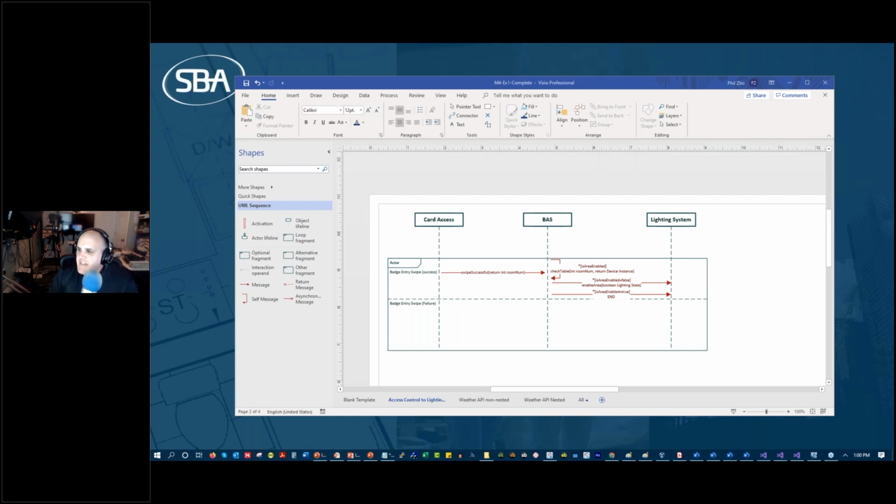How common is it to integrate BAS with fire alarm use cases? It's very common to interface BAS with fire alarm, like take a general secondary status off of a fire alarm with some dry contacts. It's not so common to do an actual integration.